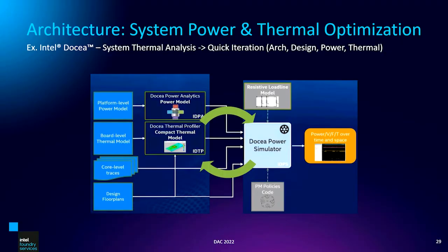Next, coupled with that is power and thermal analysis. As I look at systems today, thermal is becoming a huge concern. Rack level density, rack level TCO, rack level throughput is all about thermals, okay? So what we need to do is take this architectural model, which has all the tools for the activity factors of the workload. We need to put that into a thermal simulator, and we need to iterate with the architectural sims, the system power sims, and the thermal optimizations.